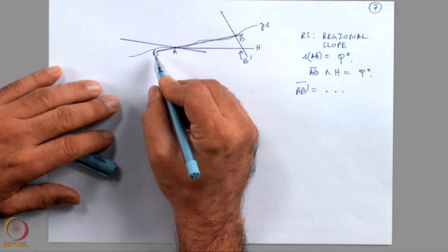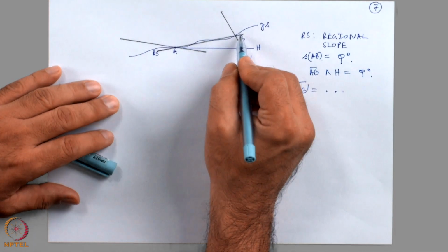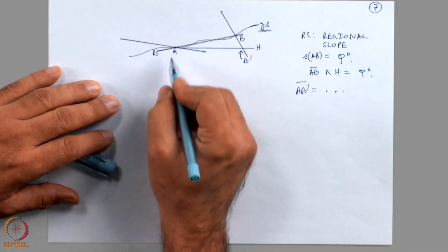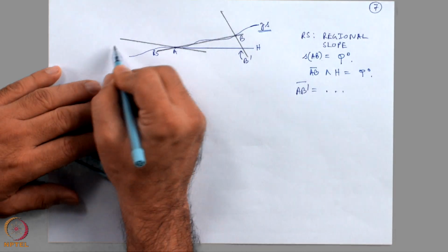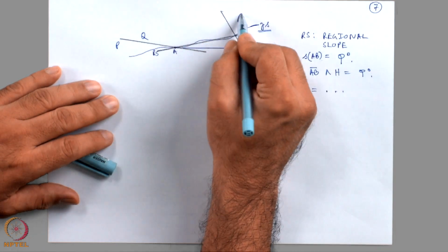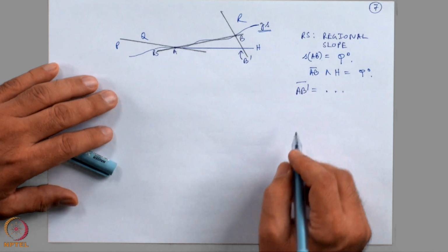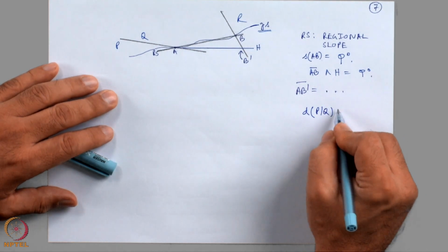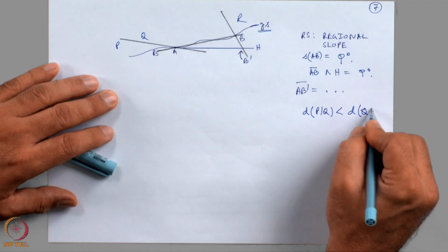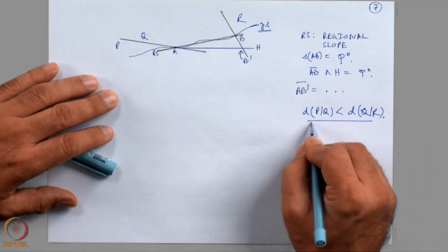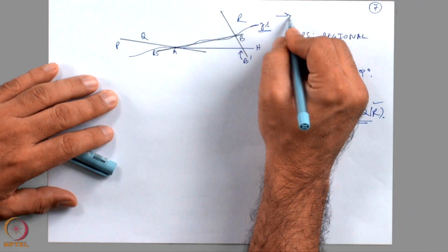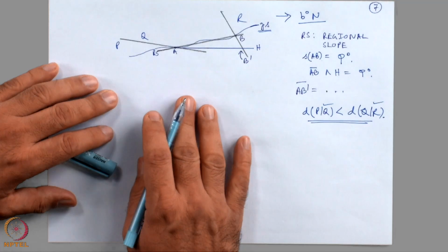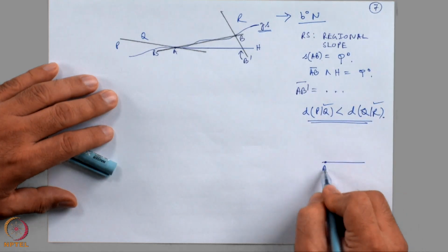Say on the ground surface, this is the ground surface GS shown by this blue pen. At 2 points A and B, the lithological contacts between rocks P and Q and R have been drawn. The situation is such that the depth of the contact between P and Q is less than the depth of the contact between Q and R, and both these contacts, this and that contact dip towards the same geographic direction, say B degree north.